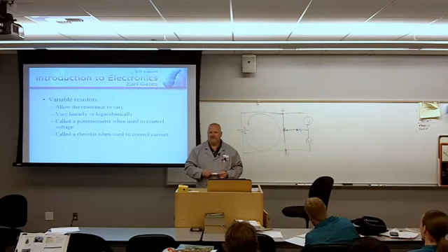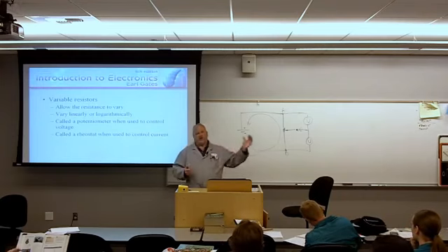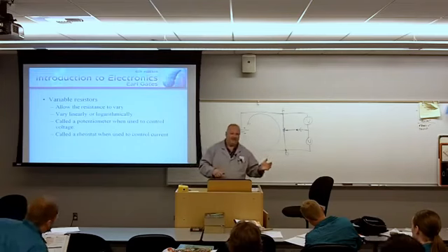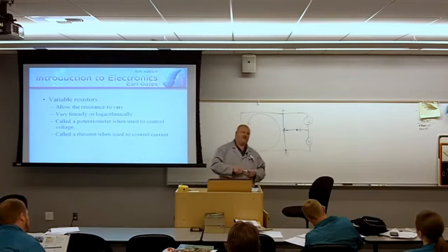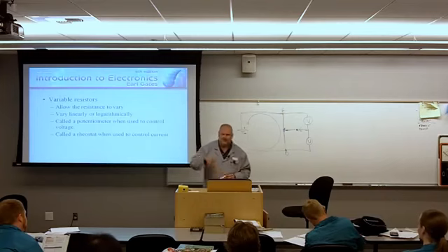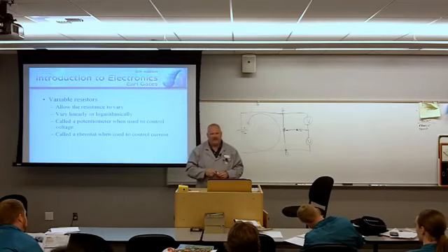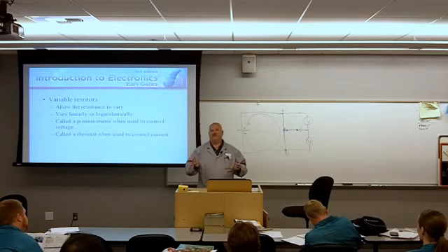How would I do that? Only connect two of the terminals. So if you go to Radio Shack and say, do you have any rheostats here? That would be a fun question. I should give you that as an out-of-class assignment. Everybody go to Radio Shack and ask if you got any rheostats. And they'd probably scratch their head and say, oh, but we have some potentiometers. You could use a potentiometer as a rheostat. You only need to connect two of the terminals.